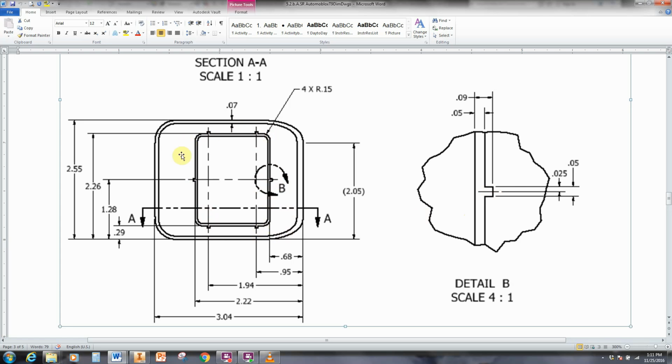So that'll be the next step. We're going to make the rectangle first. We're going to get it dimensioned correctly using these dimensions and these dimensions. Then we're going to fillet these 4 corners. We're going to give that a try. Usually I do that at the end, but I'm going to try it earlier on, filleting the corners.